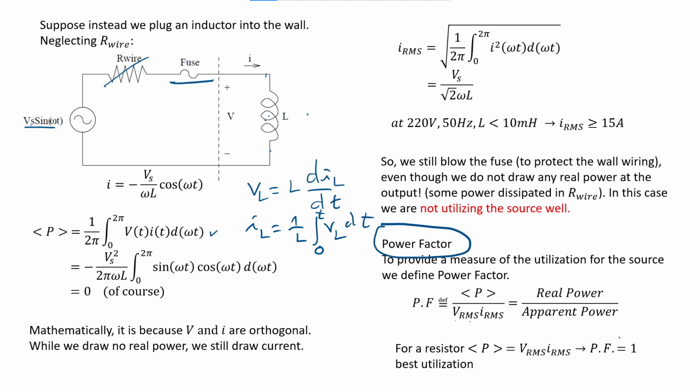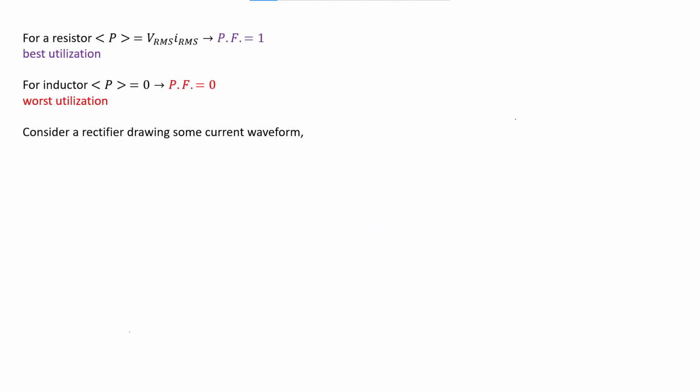Yeah. You can get power factor to be 1 if your load is purely resistor. But as long as you have inductor or capacitor in the device and component, then power factor is less than 1. So the real power is the amount of power that we use? The real power is dissipated at the resistor of the load, and the only power that shows on the watt meter. Okay, that's the average power.